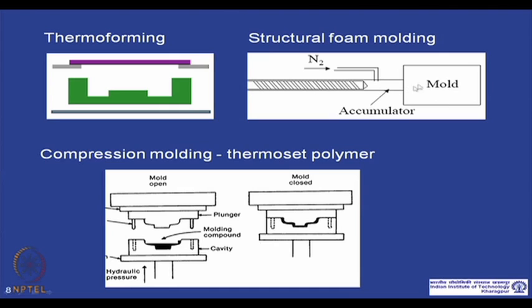So then what happens, this material fills the mold with this gas in a foamy form in between. So, the surface in contact with the mold will be plain, which will not have any bubbles. So, it will be smooth, but the bulk will have lots of inert gases as a foam. So, you can get a foamy material.